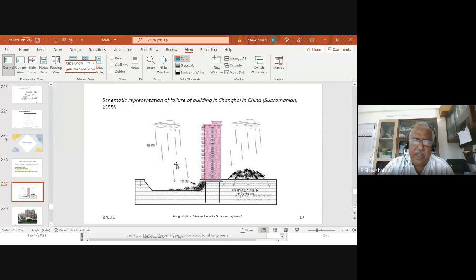So this community decided to have a swimming pool. So they excavated 3 to 4 meters on one side, and all this excavated material they dumped at the back. There was a river at the back, and one day it rained heavily. When it rains, this is a surcharge load. Soil gets saturated, so its shear strength reduces, also helped by the river water. You're removing the resisting force in the front and increasing the driving force. That means the factor of safety is continuously being reduced.